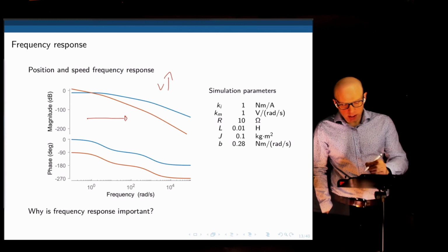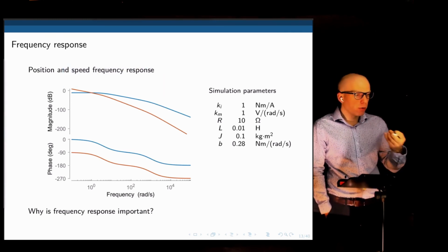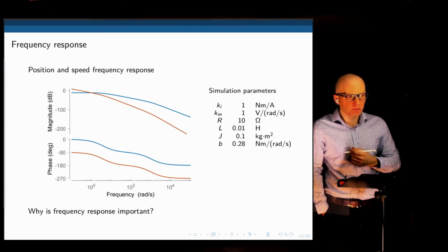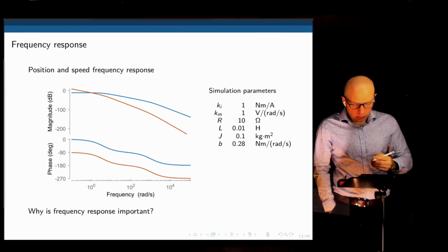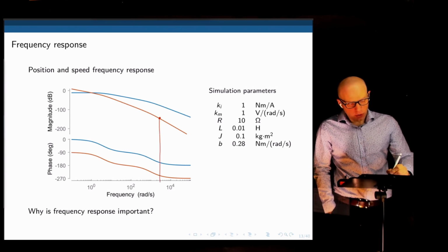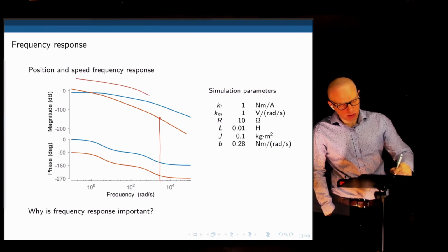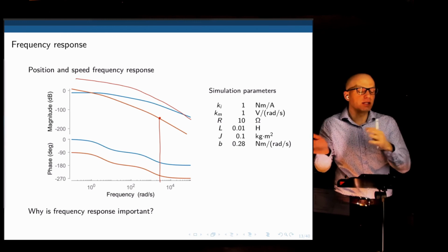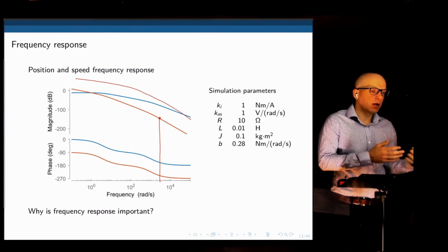So this Bode plot, in addition to telling you where these poles and zeros are and being an interesting tool to find the transfer function, will also tell you at which point you can operate your system. To have a meaningful output at this frequency here, the only way is to bump up the entire input voltage, so the Bode plot would shift up and ensure a gain between, let's say, speed and position that is still sufficiently large to provide a given output.